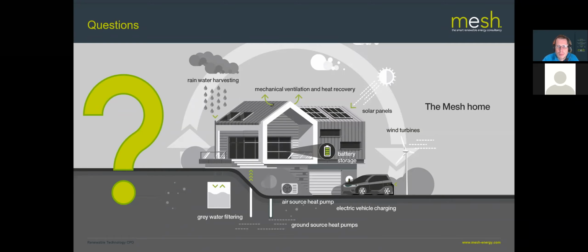There are some things that can reduce the life of an air source heat pump. Short cycling of the compressors can seriously reduce their life. So again, that's down to getting the sizing correct. And also, if you have extremely corrosive environments which can affect the evaporators, that can reduce their life.